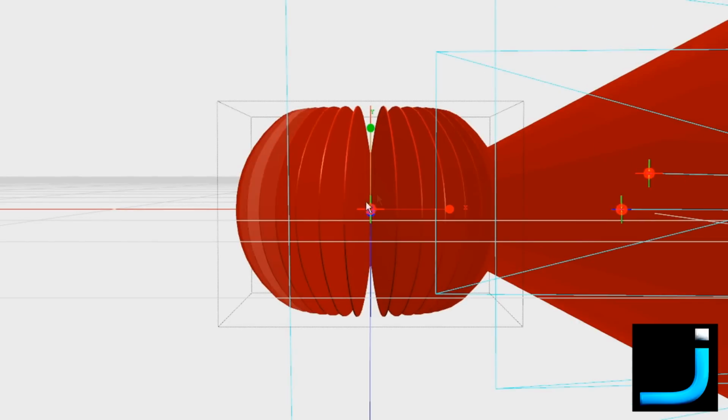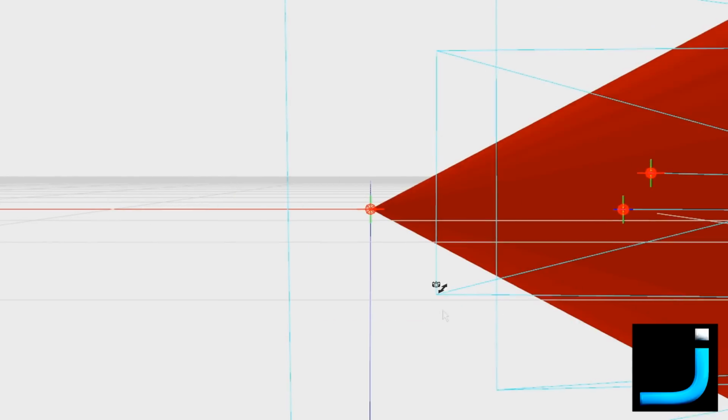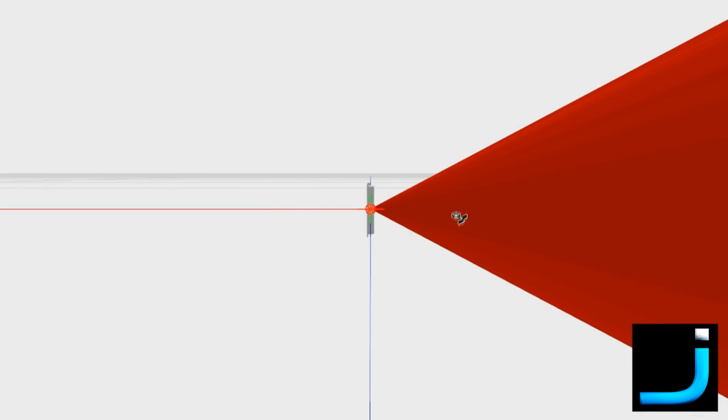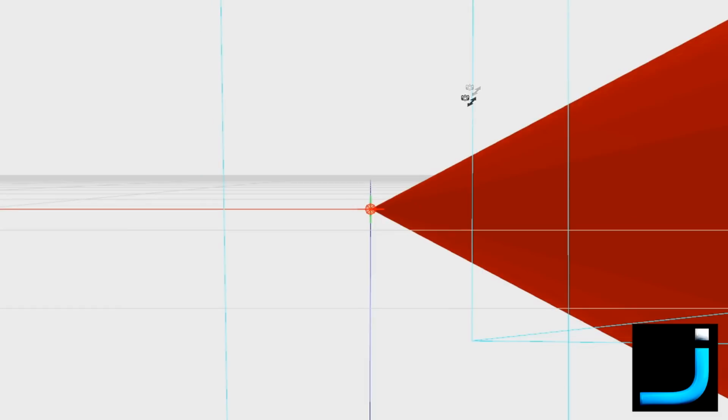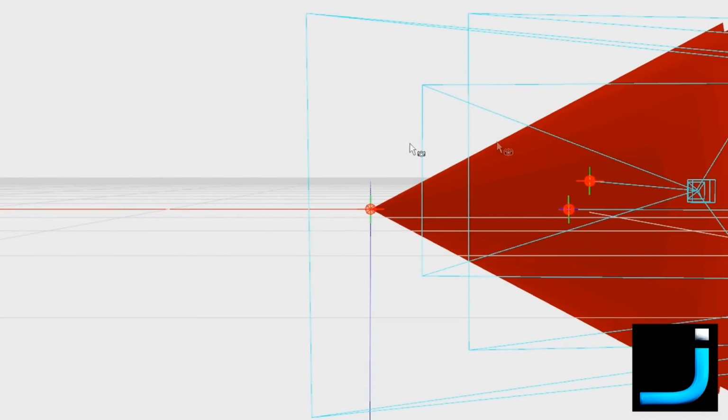So we're forward facing. There's nothing around the back for the diversity antenna. So there's no good flying behind it or above it. So one of the downsides is that it's a much narrower field of view, meaning we need to make sure the antenna is pointing very specifically at the aircraft.